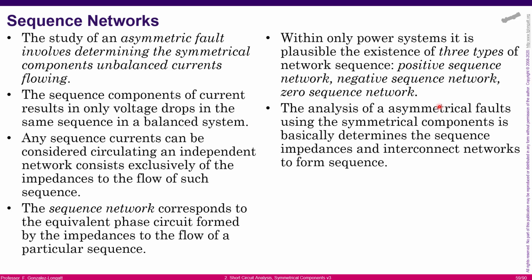To be honest, what we have done with the symmetrical faults using the Thevenin theorem is using only the positive sequence. Right now, because we are studying asymmetrical faults and we introduced the concept of symmetrical components, you must understand that when we are analyzing asymmetrical faults, we need to use the concept of sequence networks, and they correspond to the equivalent phase circuit that we create by the impedance in a very specific sequence.